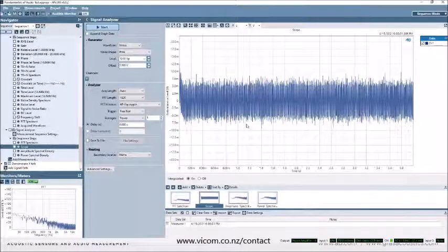Log chirps or exponential sine sweeps allow us to derive those measurement results very rapidly, usually on the order of 10 times or more faster than a traditional step sine sweep. So I would say it's a practical or a pragmatic reason to do that. In terms of the measurements, you'll get the same measurement results. One will just be faster than the other.